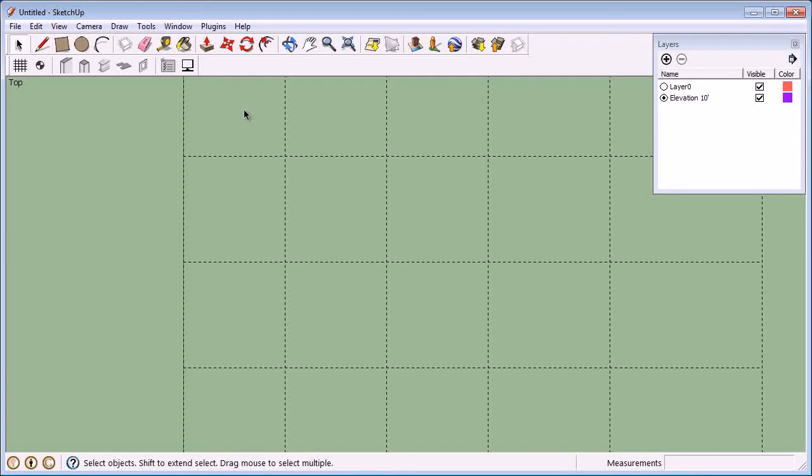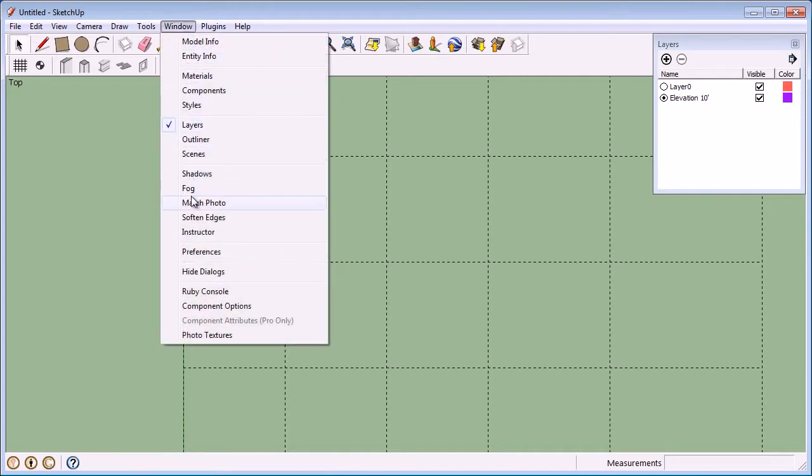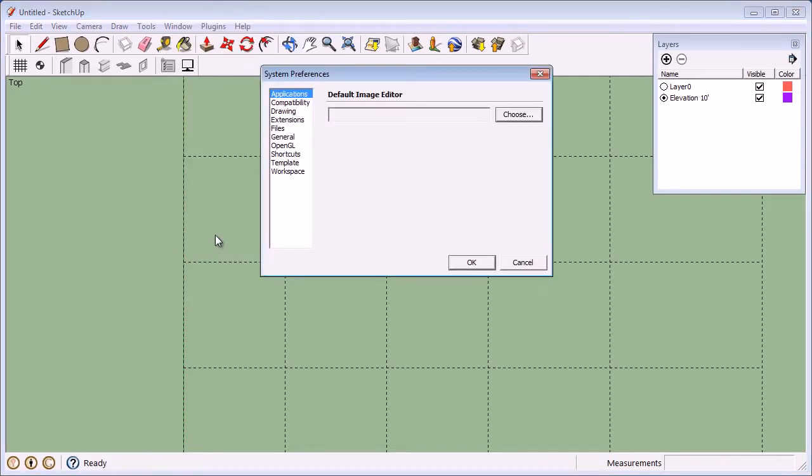In this tutorial, we will learn a few tricks that will help us to maximize the utility of the SketchUpBIM toolbar. Let's start with units. SketchUpBIM supports both metric and imperial units. If units are not explicitly entered, SketchUpBIM tools use the default SketchUp model units. Default model units are specified on the drawing template in Google SketchUp.